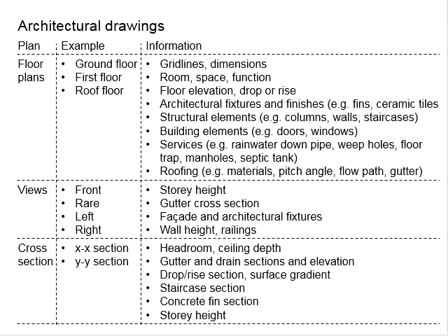You need to know that the contractor will build the structures in accordance with what you have drawn in your structural plan. If it is not drawn, you cannot expect the contractor to build it. The worst case scenario is that after building the structures, only then the contractor realizes that some mechanisms are required to hold the architectural fixtures, and whichever remedy is associated with that issue is going to be costly, and this is going to delay the project. You should have all this considered upfront before the commencement of the project.